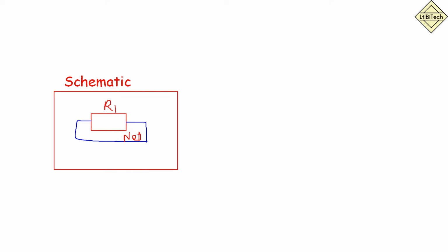So this is our schematic. Apart from this schematic we have prepared footprints, and we kept those footprints in a footprint folder. This is the SMT footprints. Till now we did this, and we also cross-checked the pin and pad mapping.